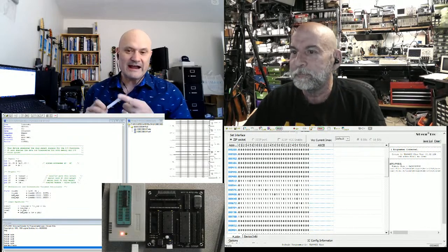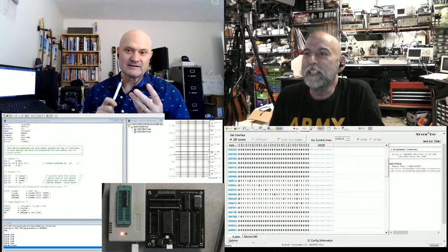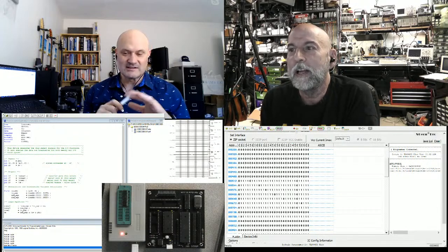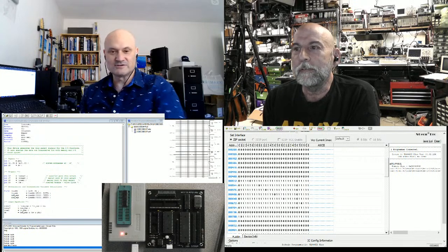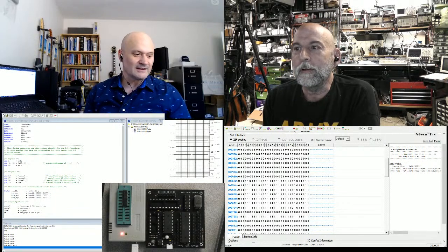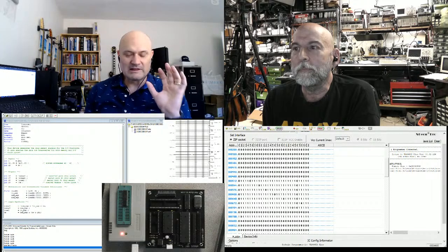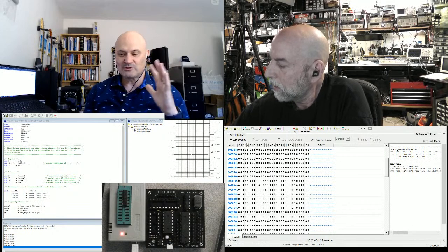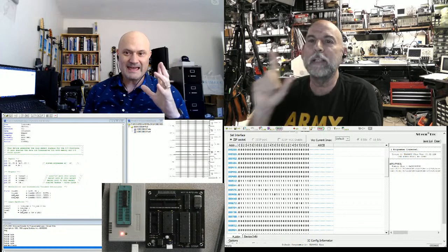You're adding more chips, more lead frames, more PCB routing, more delays, more capacitance, and more inductance to the whole system. It might be fine for a 2 megahertz thing, but what we're really talking about here is you can shrink what would be up to 5 chips down to one and have one level of speed delay.